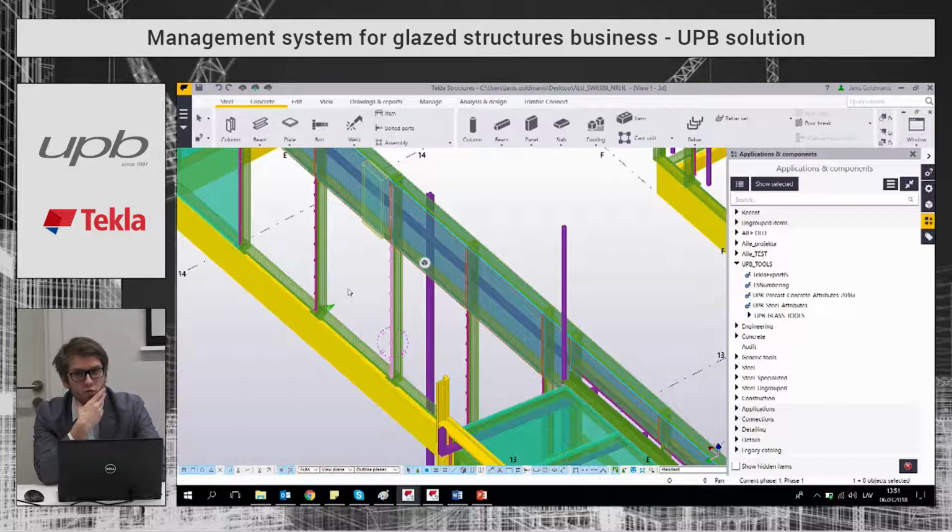And what we are currently implementing, for example, is for unitized facades. We are creating a component that first opens a wizard window where you choose what type of unitized element you will have, for example, how it is divided, usually into 4 different sections. Afterwards, you choose what type of fillings you have.